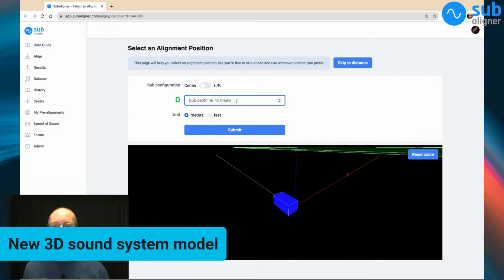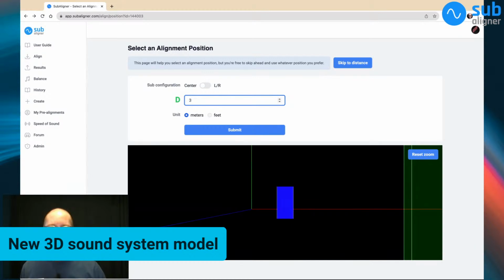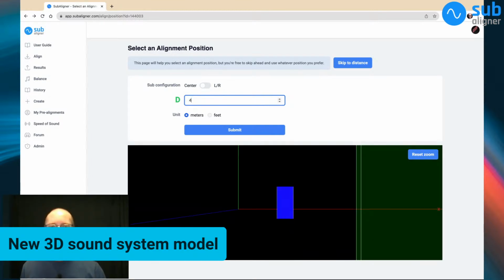So now when I click in here, it's going to zoom in to where the subwoofer is, because this is sub depth relative to mains. And so now when I start updating this, and I put in 1 or 2 or 3, you can see that the sub starts moving forward into the positive direction towards the audience on the x-axis, right?